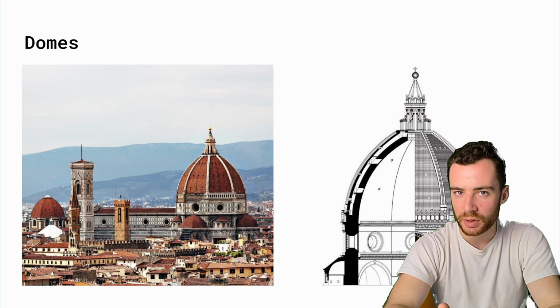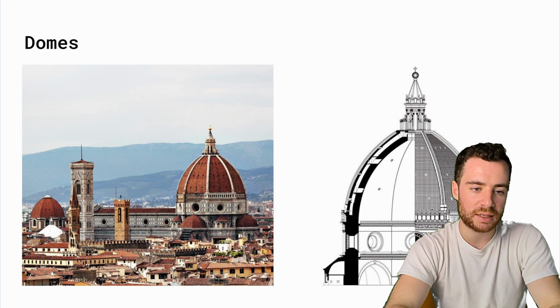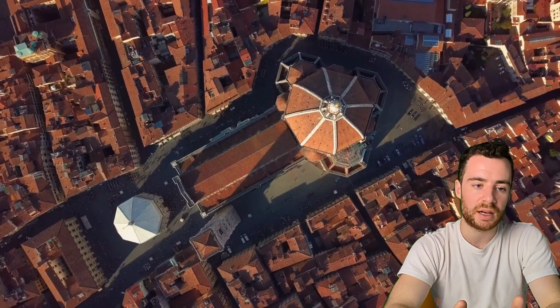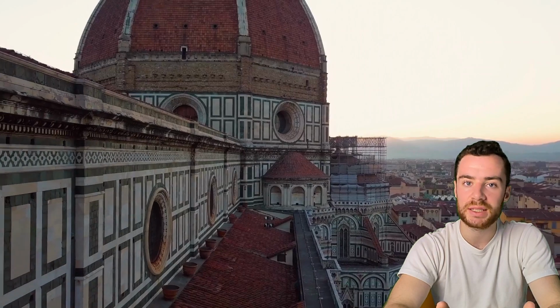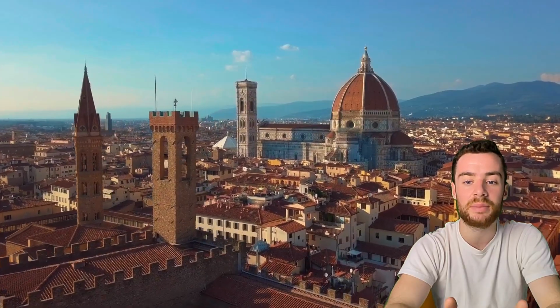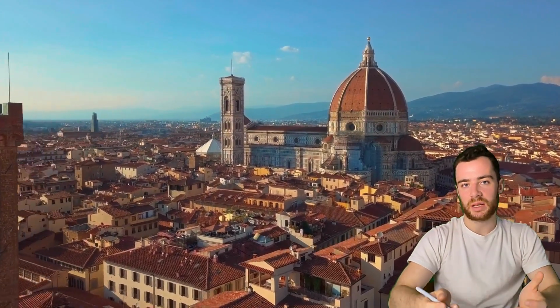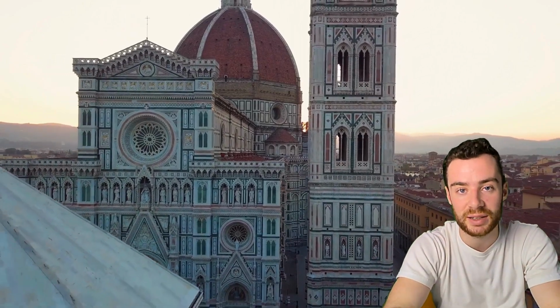An interesting example from classical architecture, you might have seen the Florence Dome by Brunelleschi, is that interestingly the detailing for it also was problematic. Due to the unreinforced masonry that Brunelleschi used for the dome, it's weakened in tension, which leads to cracking when tensile stresses exceed the limited masonry tensile strength, which means that essentially the building is susceptible to a lot of damage if there's any seismic implications happening in Florence.